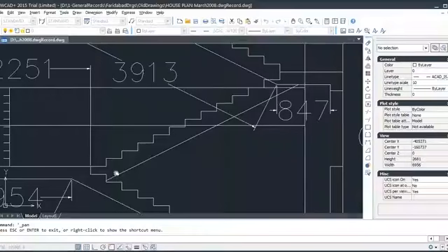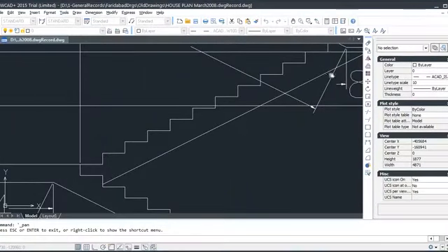This slab is called the waist slab. These are steps on this. This combination of steps and this slab is called a flight. We say it's a flight of stair. These steps must have reinforcement, and the stair must have reinforcement together, and these should be cast at the same time. What I see is people cast this and forget this, and cast this later on. This is the mason's technology, which is incorrect.